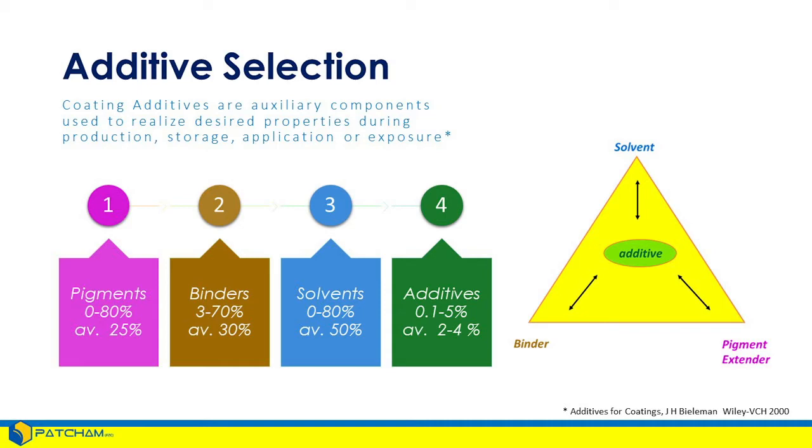And the combination of those three cannot be made into paint unless number 4, the additives, are a part of the formulation. It's the additives that are a critical part of the formulation, but the selection and the amount of additives used is dependent on the composition and components and the percentages of the pigment, the binder, and the amount of water in the formulation.